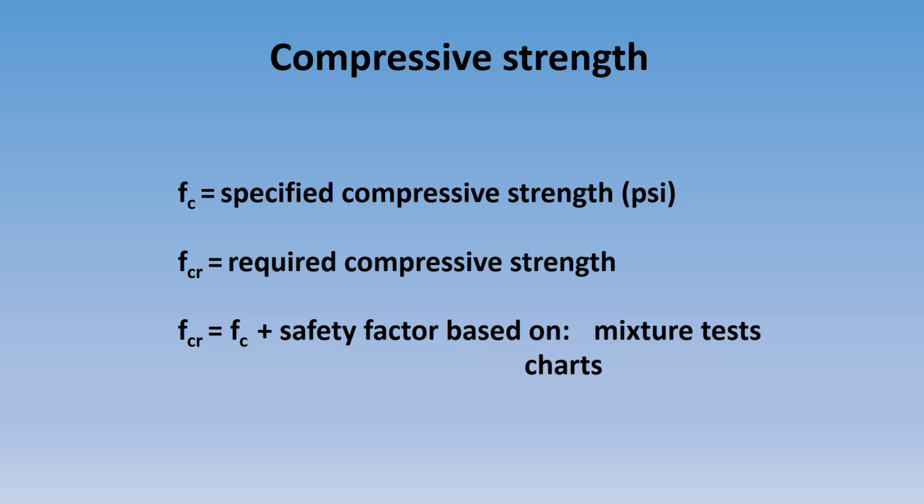These safety factors are real common, like in architecture, right? Architects, when they're designing roof structures, if you're in an environment that can expect 40 inches of snow load a year, you add in a safety factor of 2, and you design a roof to withstand 80 inches of snow, right? Same thing with concrete. You build in a safety factor to ensure your project won't fail.